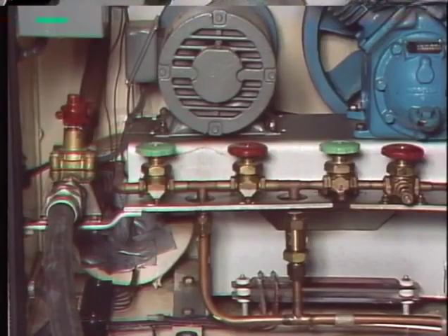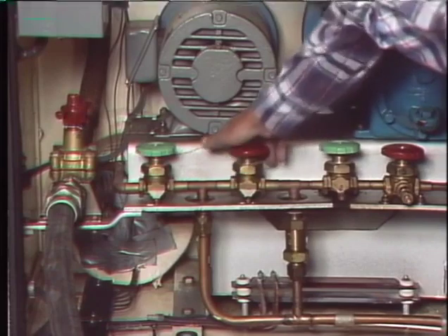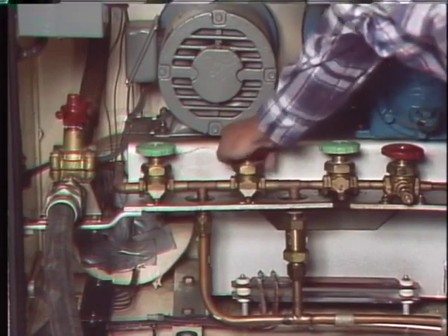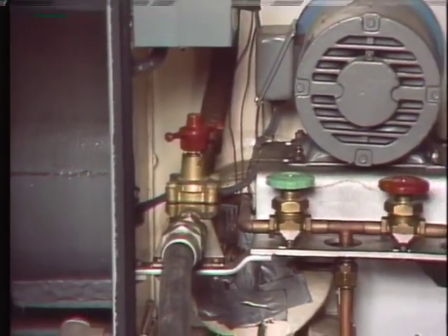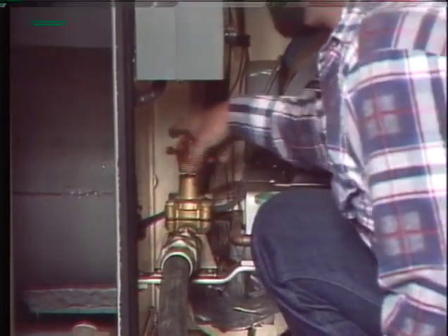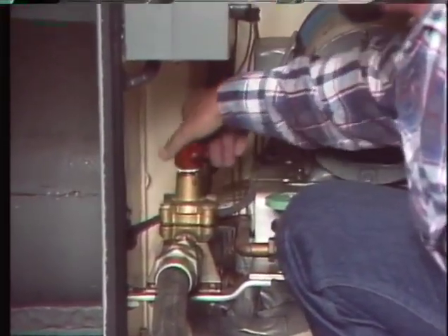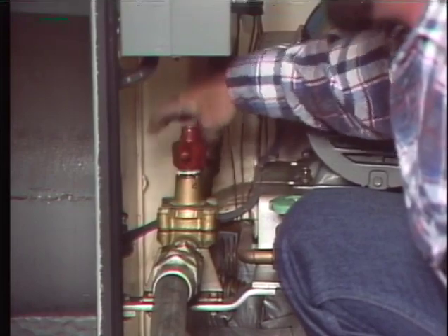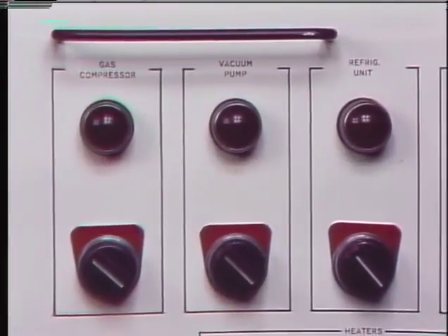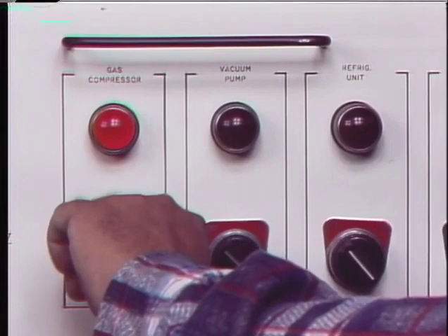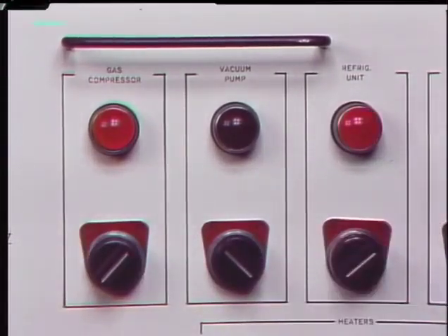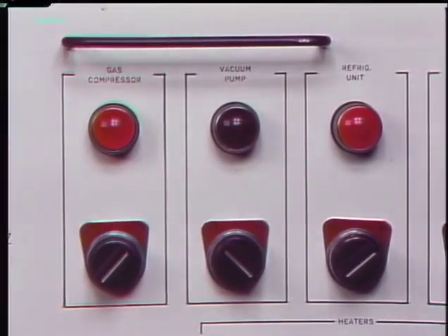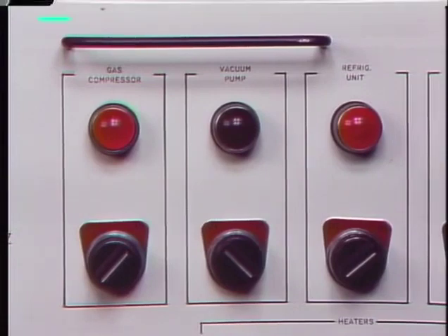Next, a valve is opened at the breaker to allow gas in the high-pressure system to flow to the low-pressure system and equalize the pressures. When the pressures have equalized in the breaker, a main tank cutoff valve is opened to allow the gas to flow from the breaker to the storage tank until pressure between the breaker and the tank equalizes. Then a compressor is started at the trailer to pump the gas out of the breaker. A refrigeration unit is also turned on to keep the gas from heating and expanding as it's transferred into the storage tank. The compressor is allowed to run until all the gas has been evacuated from the breaker.